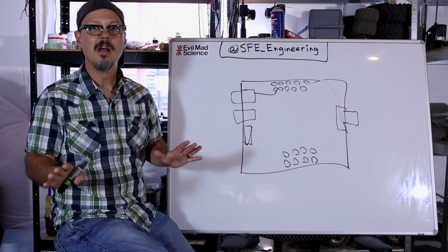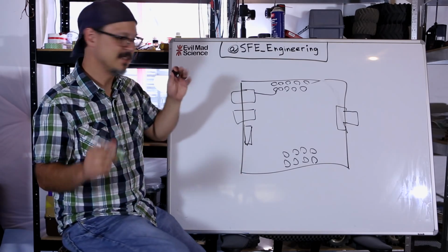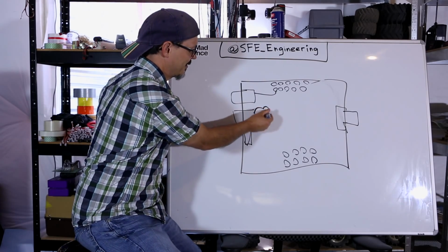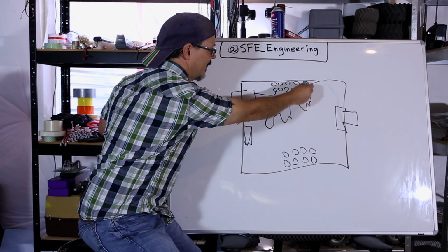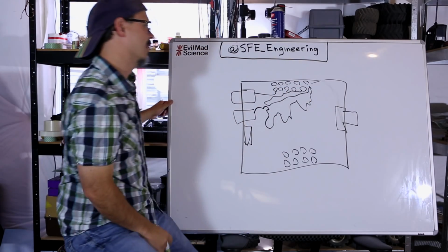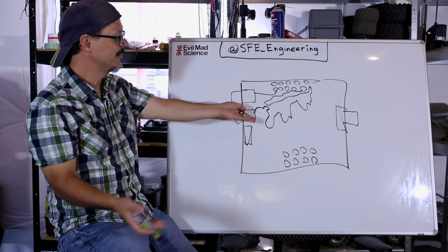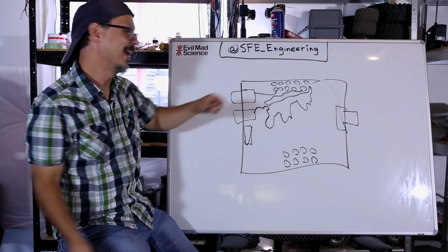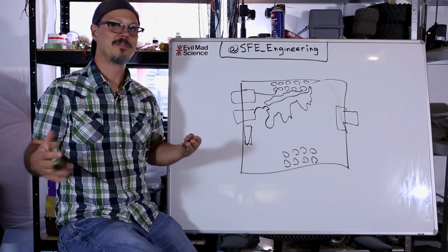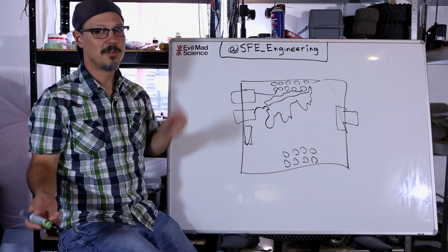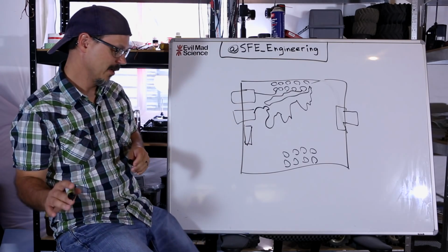Other thing, don't use an auto router. I mean, if you can help it, right? Because auto routers do things like, hey, you want a trace over there? Okay, there you go. Okay, that looks awful. And that's an antenna. So you don't want that. You want to keep your traces nice and elegant, and an auto router is generally not going to do that for you, so you probably want to stay clear of that.